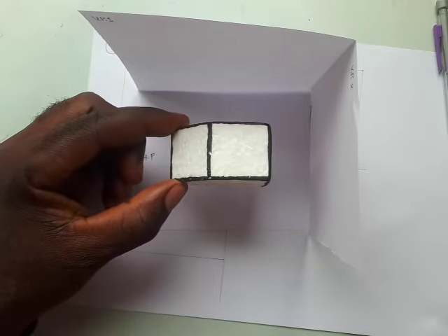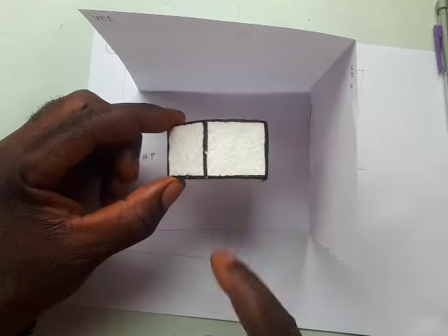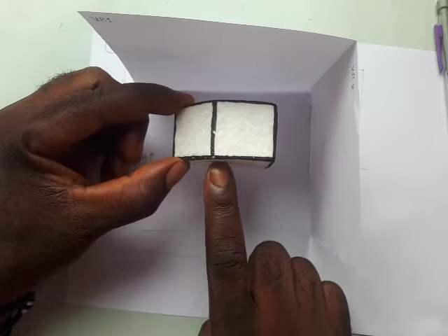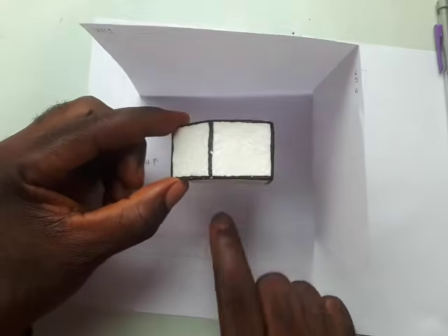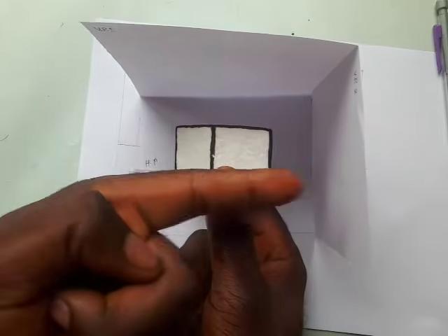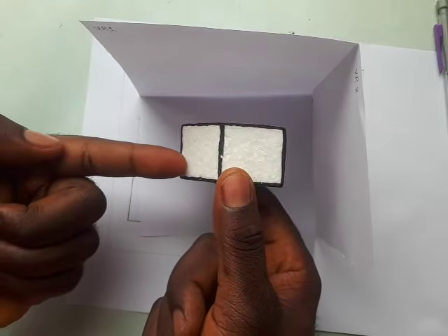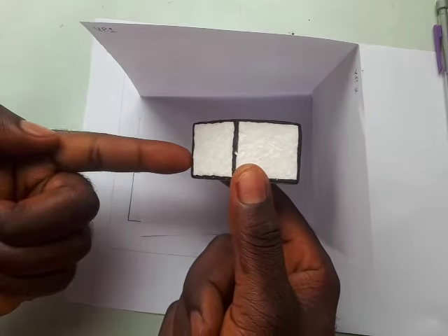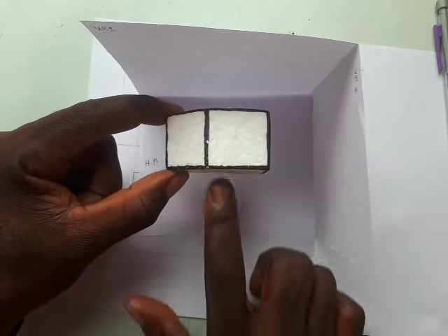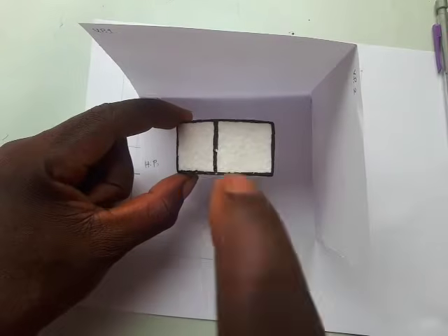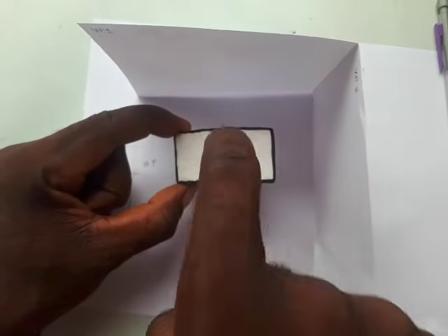All right. Now, this is where auxiliary comes into play. Auxiliary is neither here, because we are viewing perpendicularly. This is front elevation. If you are viewing from the side perpendicularly and you are drawing on this plane, this is another view, that is end elevation, because it is perpendicular to this surface. Now I'm moving here and I'm viewing perpendicular to this surface.